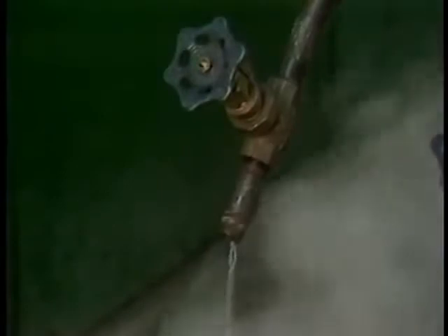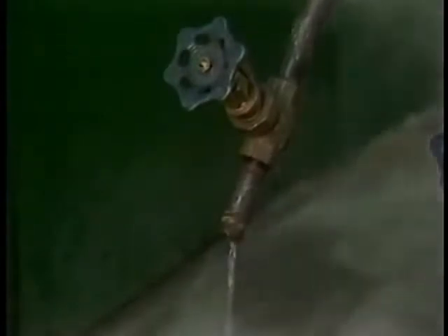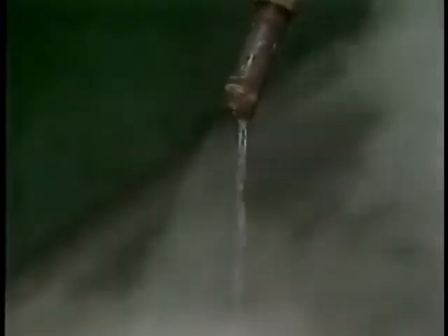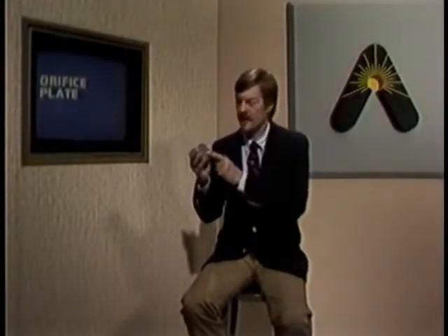Initially, condensate was removed by simply cracking a valve, wasting the hot condensate and some steam as well to the atmosphere. The next step in condensate removal was the application of an orifice plate. These plates were simply discs drilled with a fixed hole or orifice. They were inserted at the steam line drip point or equipment discharge line, draining condensate and venting non-condensibles from the steam space. The orifice plate had its problems, though.